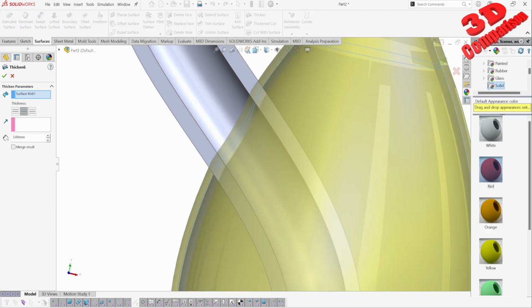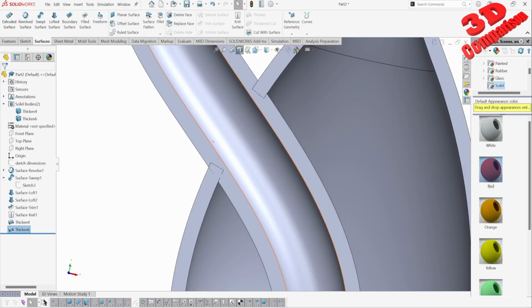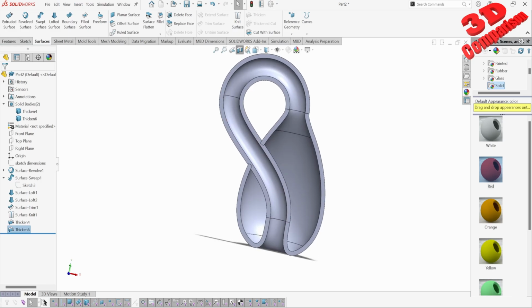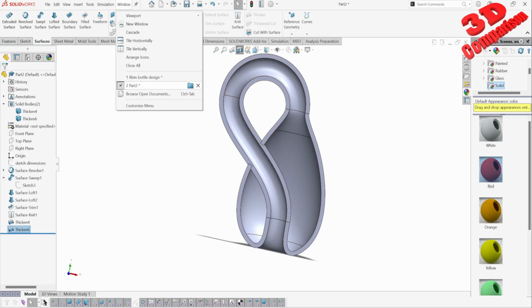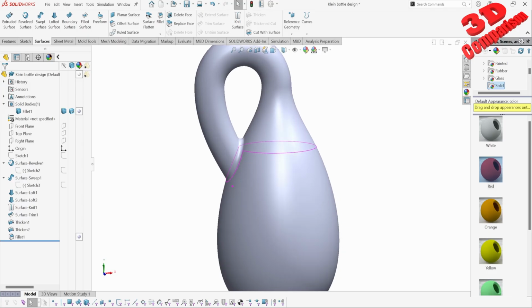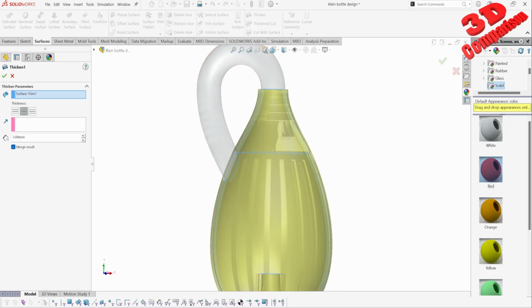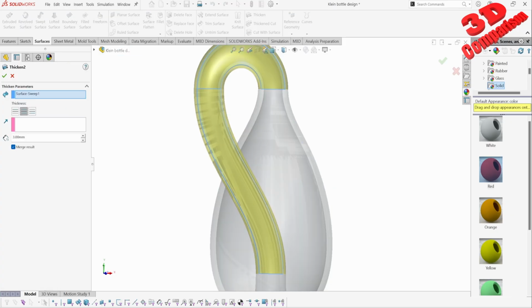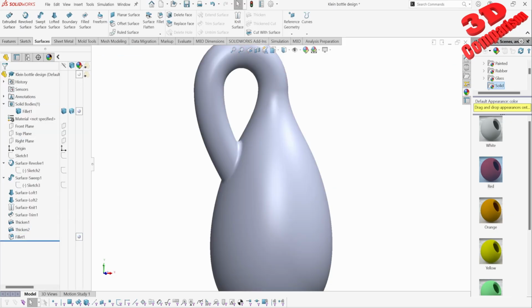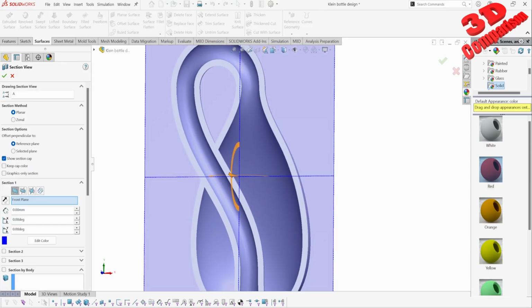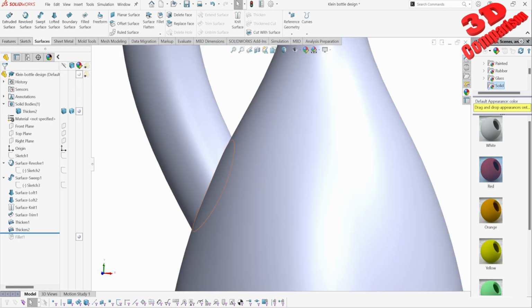And if I try to have that merged, we see that this will have the following troubleshooting. Now, in this case, we have the possibility to change the sketches a little bit, because, for example, within this bottle that I created previously, you see we have a thickening of 3 with merge results, and the second will be over here with 3 millimeters. And this worked. I also added a fillet afterwards. So within the section, those two profiles look like this.